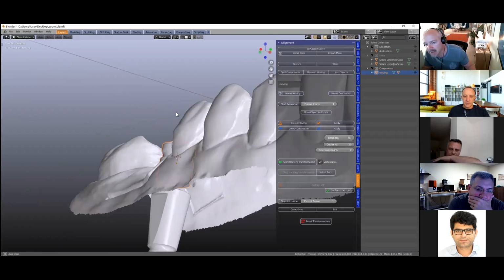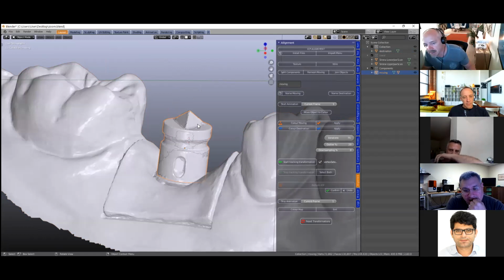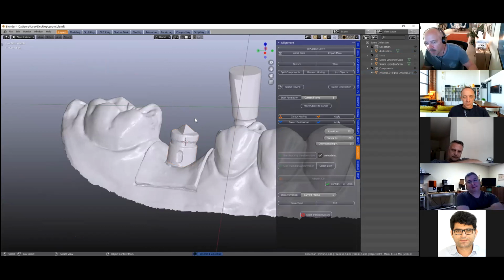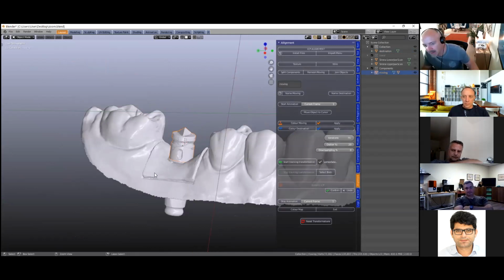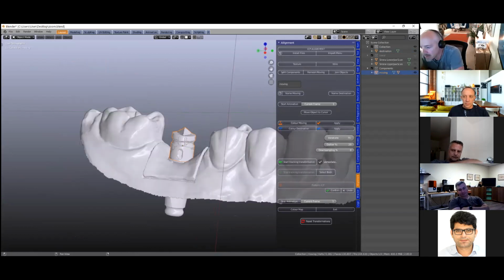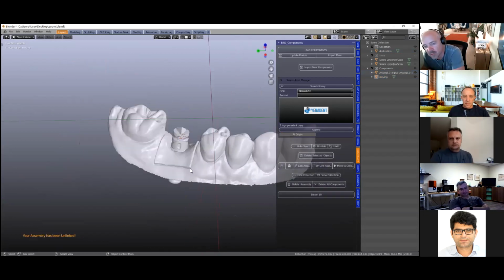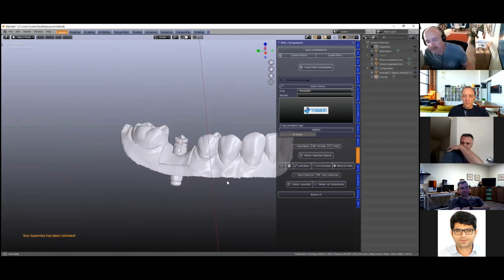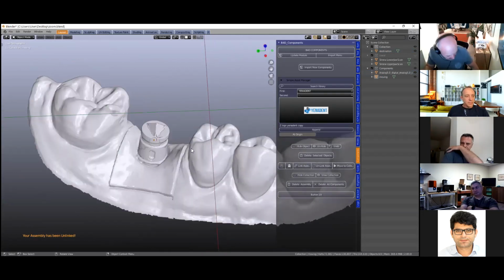This one is linked. So if I take this scan body and delete it, so if I go X delete, that one will clip back to where it was, because it hasn't taken the orientation. So in the component model, we can just click unlink, and now it's unlinked and it's perfect. It's ready to go for our next step to make a model. So yeah, I'll just take a drink. If there's any questions, please just ask.